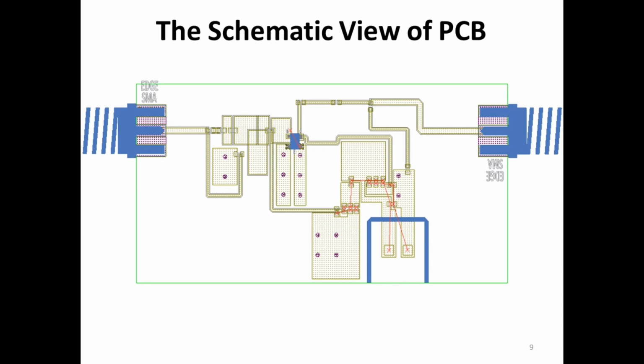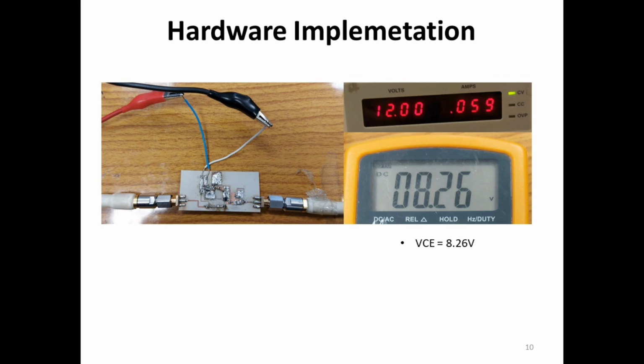By using microstrips and the HSMA connectors, I simulated the PCB design of the amplifier. I provided via holes for the ground pads. In the hardware implementation, I connected these via holes through wires. Then I soldered surface mount components.